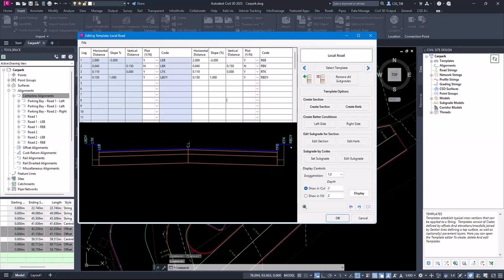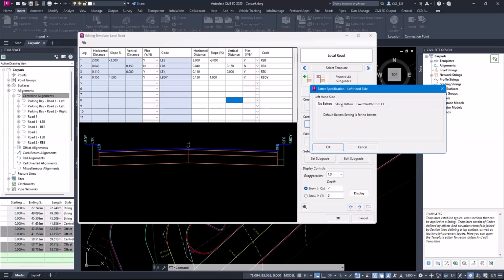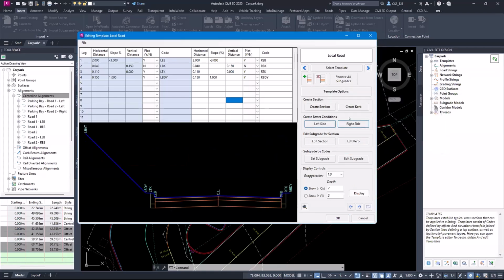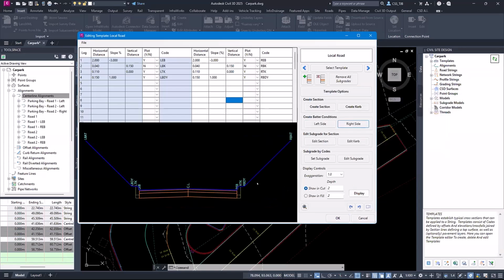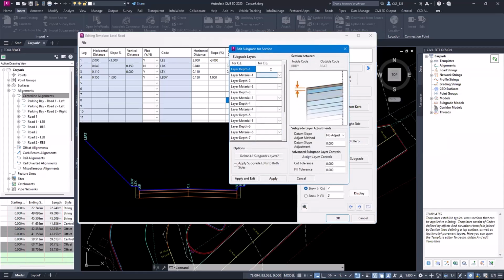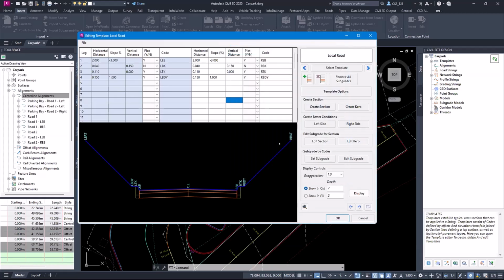And when I do that, because I've done that, when I get to the subgrade model, the subgrade will build the bottom datum of everything, including the bits that parallel up with the design at zero depth. I'll retouch on that when I get to the whole effort of making the subgrade model. So there's the left batter, something generic. We'll just go 1 in 1. But I'm also going to do that same idea of zero depth on the batter as well, so that my subgrade model will extend right through to the back code on the left and the back code on the right.